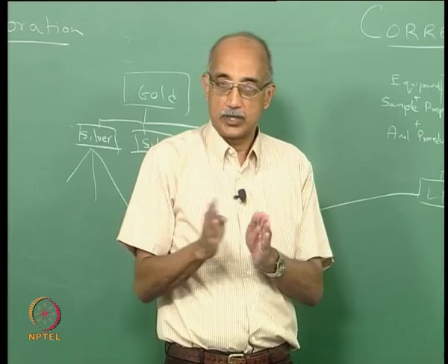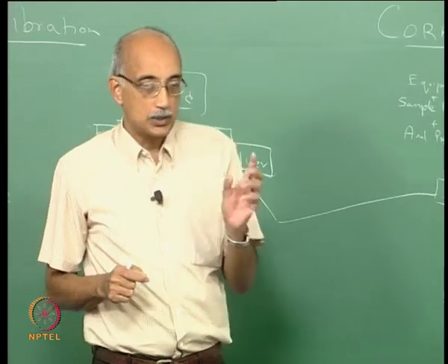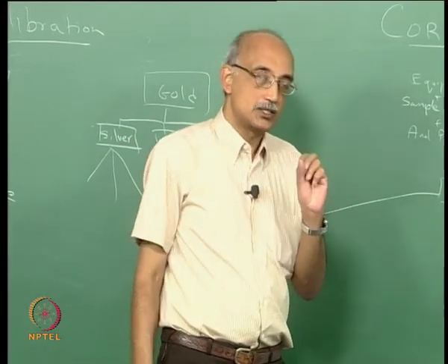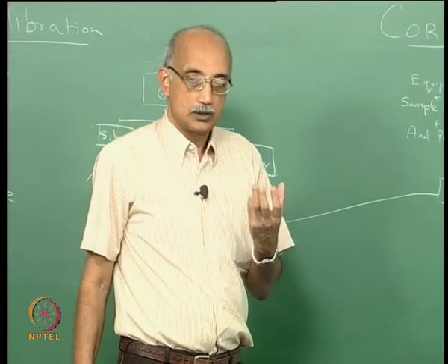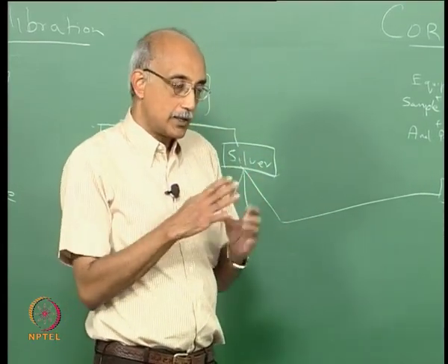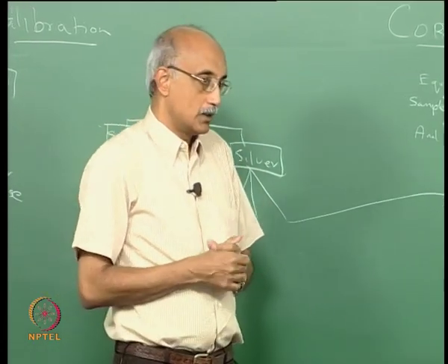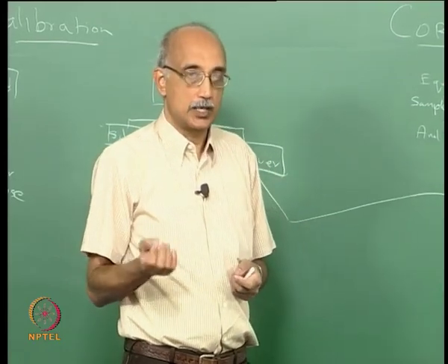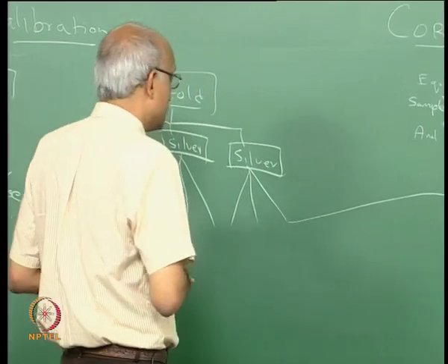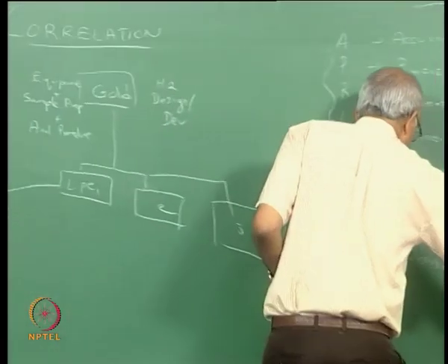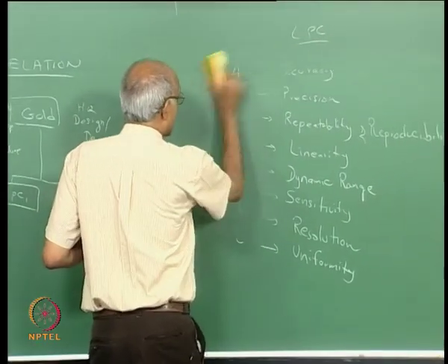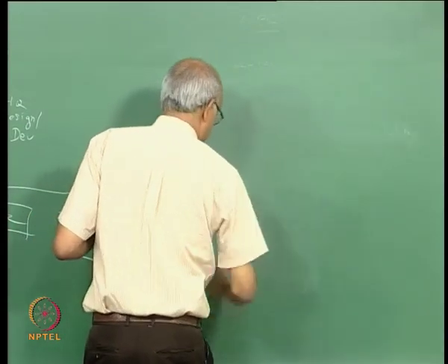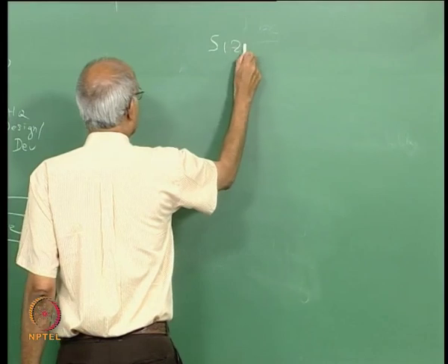Now those two are again very different, because if you are only doing count calibration, then that is once again primarily a measure of the sensitivity and other properties of your instrument itself. You can prepare a set of standards which may be particles of a known size, and by the way the most commonly used standard is polystyrene latex. PSL as it is known is widely used as the calibration material for size calibration